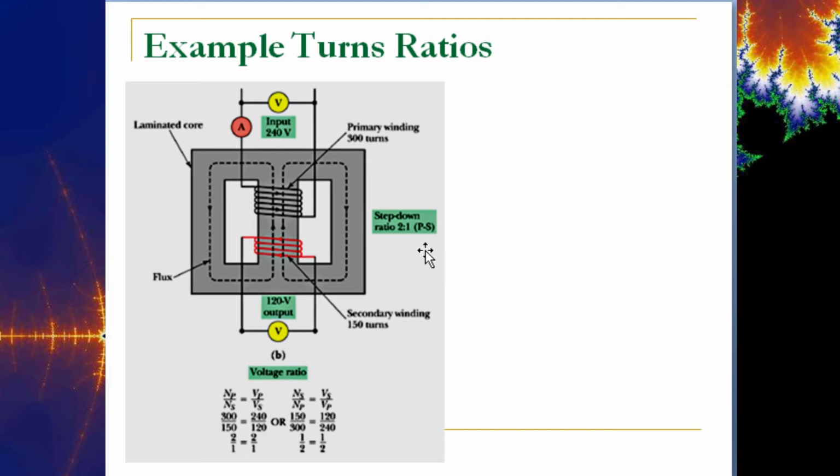And it's always a good idea to note, sort of off to the side, what you mean by this ratio, because if you just invert it, if you take it to the -1, it's a 1-to-2 ratio. So always note that typically we do this with primary to secondary. We say 10-to-1 or 12-to-1 or whatever it is. But it's always a good idea to make sure that whoever's looking at it knows that you mean primary to secondary ratio. Okay, so if that's the case, we have half the voltage available on the output. Here we're saying on the primary we have 240 volts, which means half of that is going to give us 120 volts on the output.